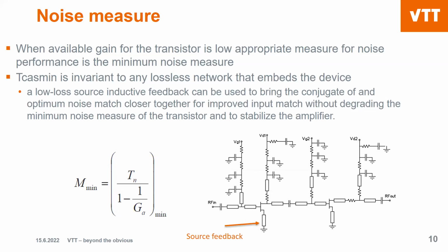But if we have really low gain, like 5 dB, all of the stages start to affect the noise figure of the receiver. There was that Friis formula which we went through. So if we have several amplifiers with low gain, all of the amplifiers start to affect the noise figure of the receiver. So this is important to at least remember at this point, since we are microwave engineers.